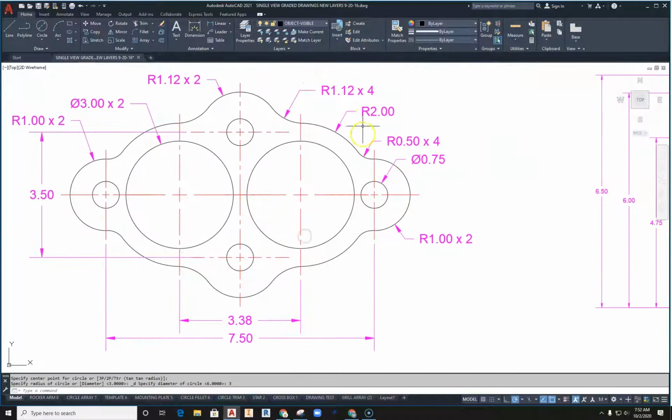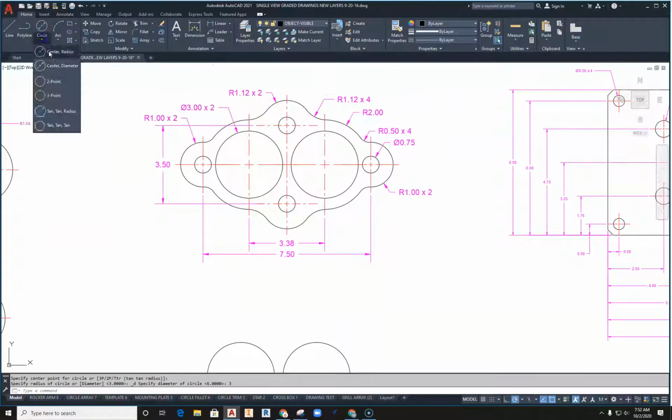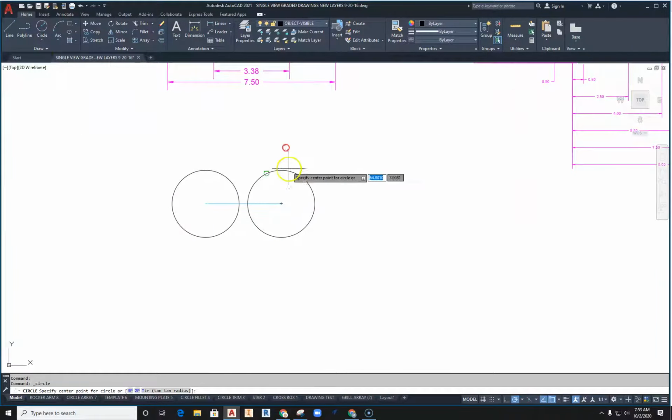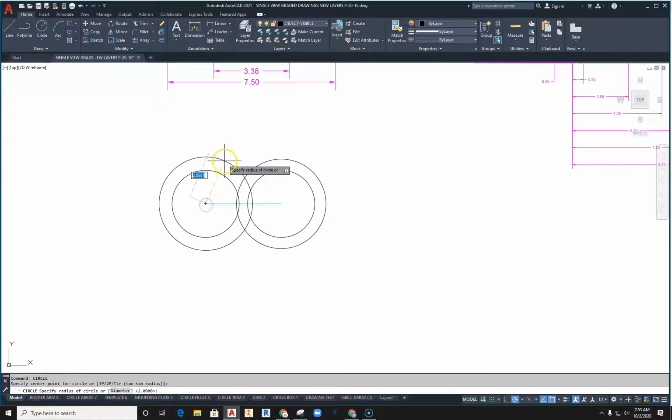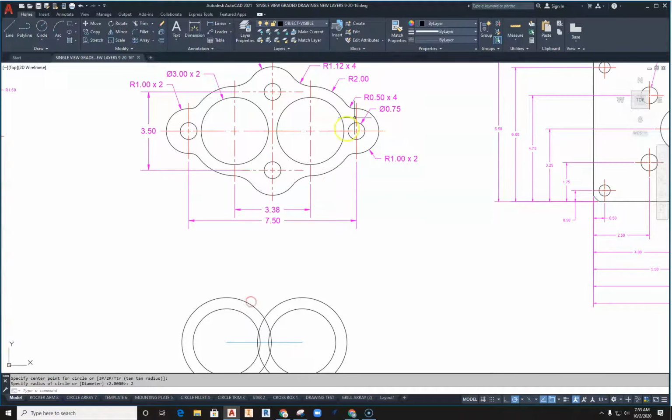Well, I can go ahead and now create this radius circle next, because that is now concentric. As this extends out past the edge of that arc, that is concentric, so that's going to be a radius of 2. So we'll keep building those out. So grab the radius circle, find center, pull out, 2. Do this again, repeat circle, 2. So now I have those set up.